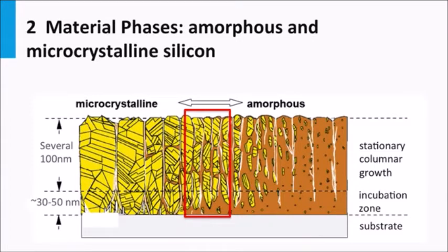The bandgap of nanocrystalline silicon is close to that of crystalline silicon due to the crystalline network in the grains. The bandgap of amorphous silicon is larger in reference to crystalline silicon. It is out of the scope of this course to discuss this in great detail, but the distortions in bond angles and bond lengths make the bandgap larger in reference to the crystalline silicon lattice.